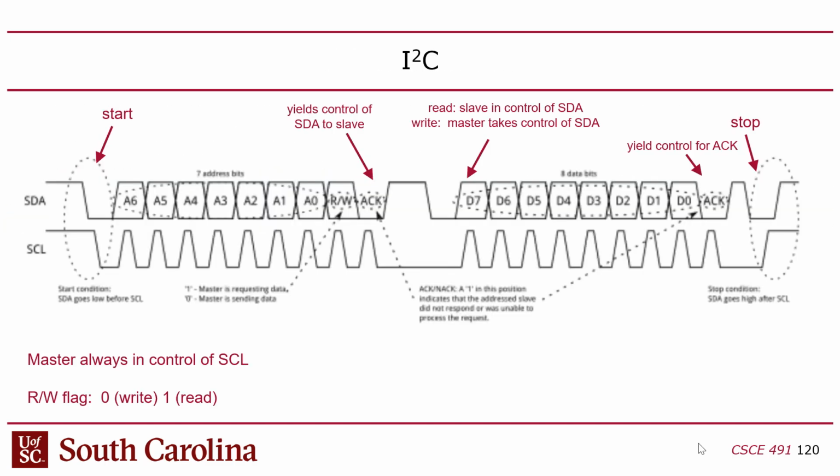Now the transition that happens is different between start and stop. In start, the data is being pulled down when the clock is high. And is it the opposite? Yeah, it's the opposite over here. Notice that the data is being pulled up when the clock is high. So the start and stop is changing data when the clock is high, but more specifically, pulling down the data when the clock is high is the start, pulling up the data when the clock is high is the stop. Right? I got that right?